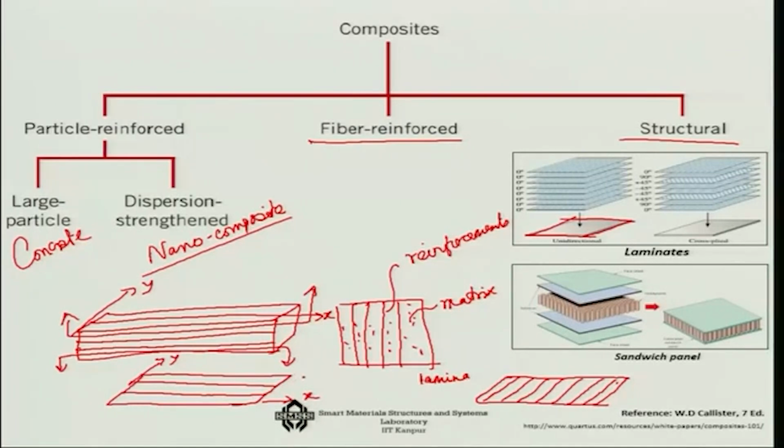Here the angle theta equals 0 degrees, because with respect to the x axis, or the longitudinal axis, the angle of the reinforcement orientation is 0 degrees, whereas here with respect to the x axis it is 90 degrees, and hence this is a 90 degree ply. I can thus have 0 degree, 90 degree, or anything in between, 30 degree plies or 45 degree plies, etc.